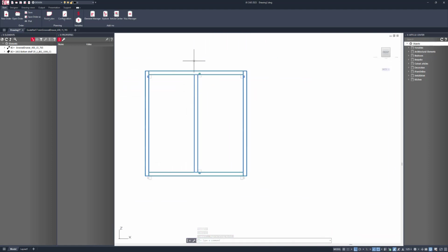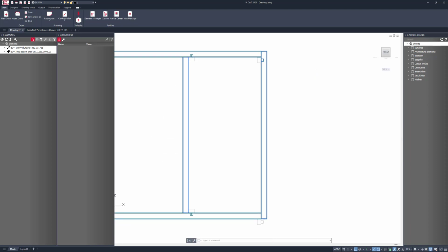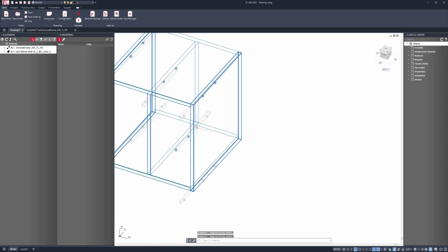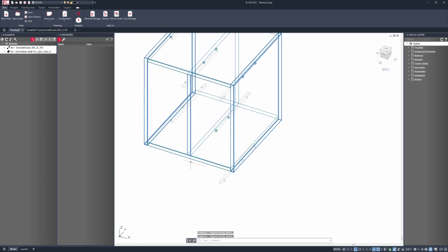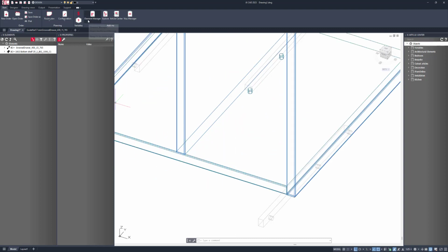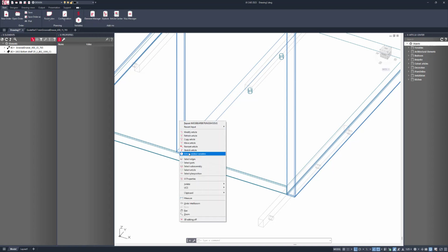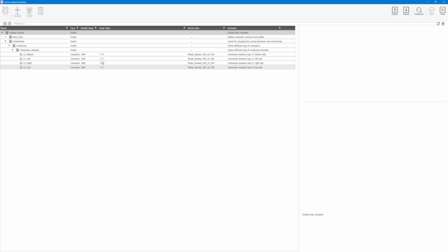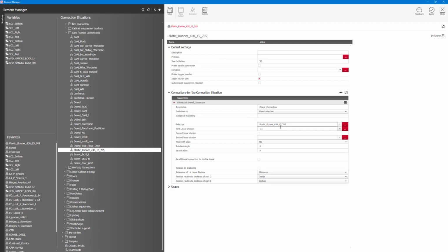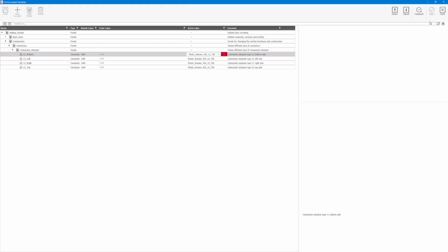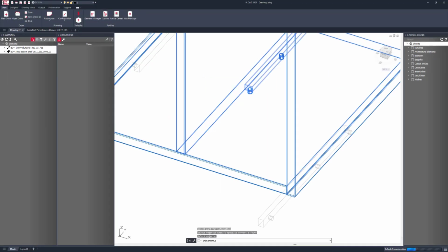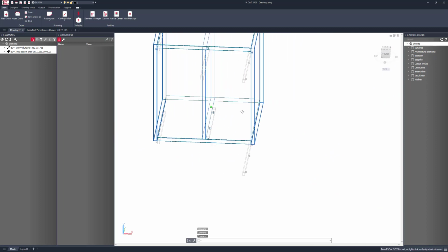So don't worry about the fittings around the outside. These wouldn't be used. So effectively now what I can do is change my linear divisions, because that's what's controlling the position along the length in here. If I go back to the article related variables, I can say this should be, not 1:1, but maybe 10 mil to 1. So that's going to bring it up close to the front leading edge. And then if I refresh, that's going to bring it nice and close up to the front here.